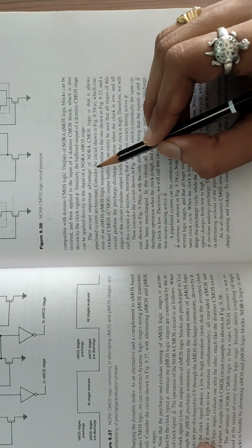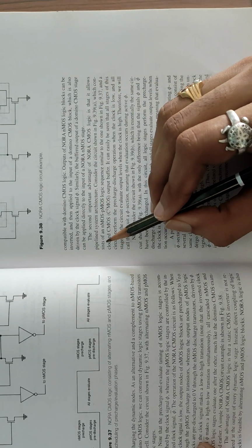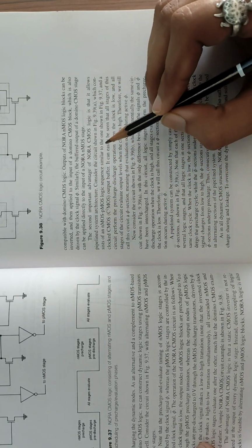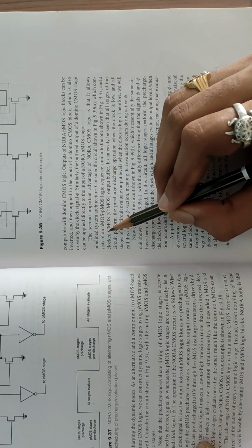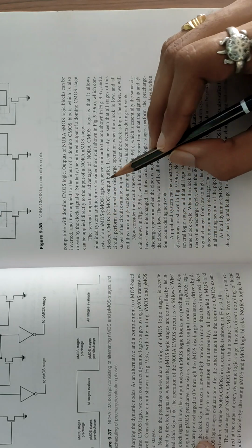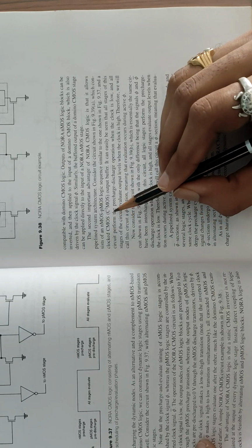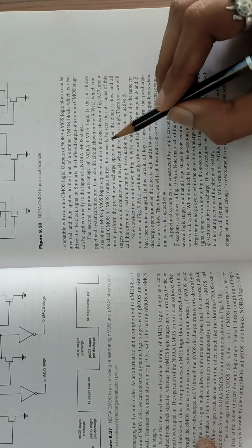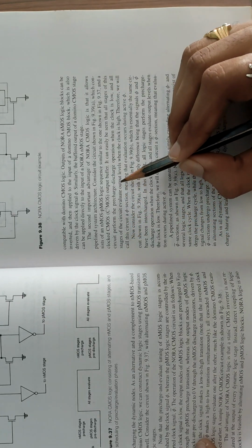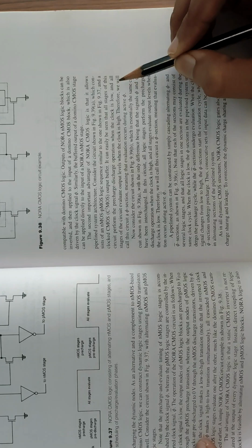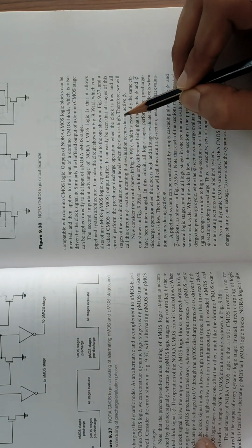The second important advantage of NORA CMOS logic is that it allows pipeline system architecture. Consider the circuit shown in figure A, which consists of an NMOS-PMOS logic sequence similar to the one shown in the figure and a clocked CMOS (C-squared MOS) output buffer. It can be easily seen that all stages of this circuit perform the precharge-discharge operation when the clock is low, and all stages of the circuit evaluate output levels when the clock is high.